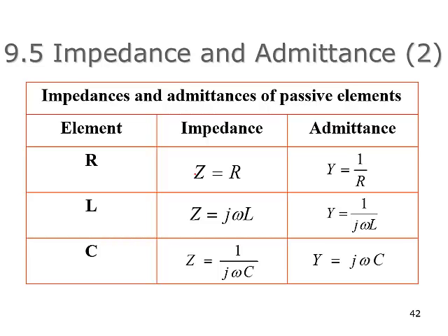And again, if you're adding to that table, you might think about adding another quantity here for Z, which is the impedance of these different devices. The impedance for resistance is R. For an inductor it is just j omega L. For a capacitor it is 1 over j omega C, or minus j over omega C. It tends to be a little bit easier to keep the j in the numerator. And then admittance is the reciprocal of all that.